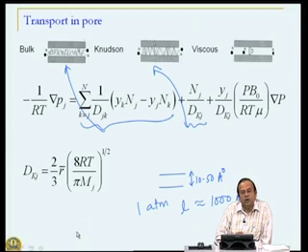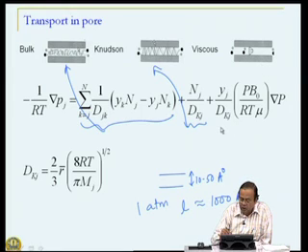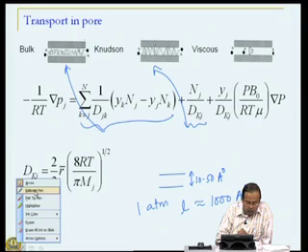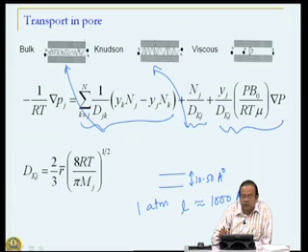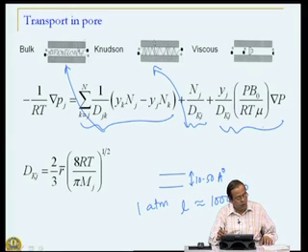The third phenomenon by which material can flow, particularly when we are looking at pores as capillaries, is that from inlet to the outlet there will be significant pressure drop, and this pressure drop will drive the flow of material through the pore. This is referred to as viscous flow, and using Darcy's law, this can be represented as the pressure driven force through the catalyst pellet.